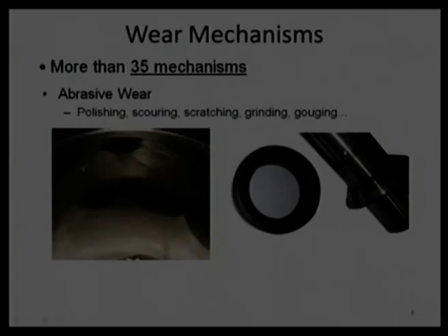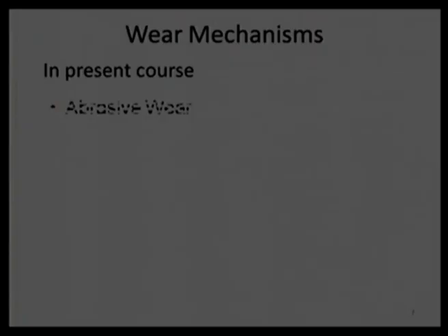Now, if somebody by mistake thinks, oh, this surface is getting dirty, oh, some black marks are there, I want to polish at every new operation and get good performance, then he will be mistaken. This layer has been deposited intentionally. It has the basic physics behind that, and if somebody without understanding it tries to remove, no, this is dirty surface, it should be cleaned before assembly, then he will cause unnecessary failure of the component, unnecessary wear of a surface, and higher power loss. So, that is a polishing wear, right.